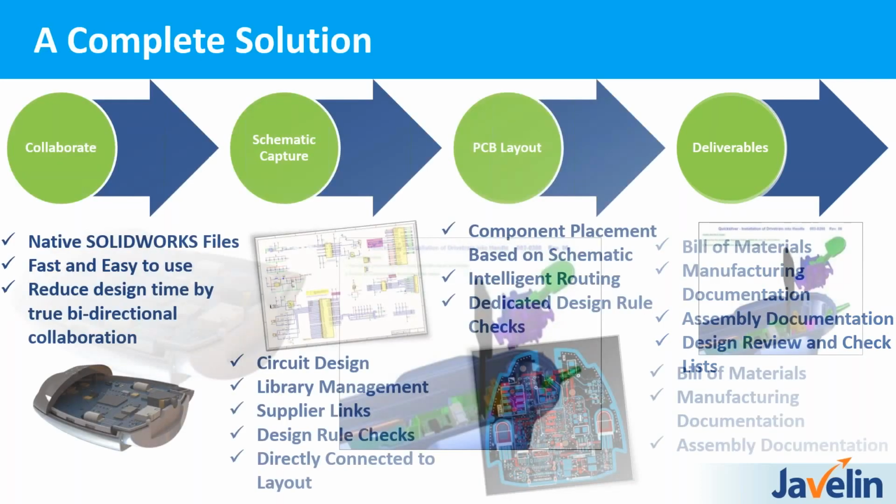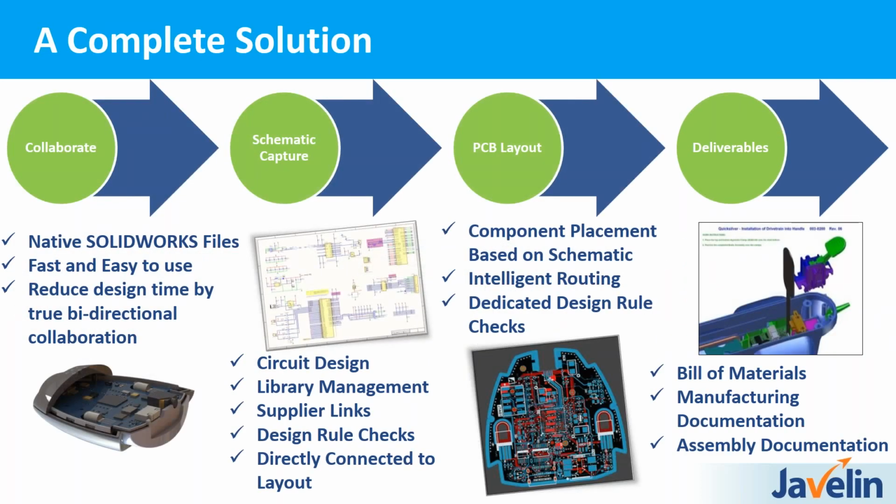So with that, it is a complete solution. We are able to work in a native SOLIDWORKS environment. The information is bidirectional between the two applications. We can work in a schematic capture environment where we have all the information from a schematic perspective. You can manage our libraries really well. Design rule checks exist both on schematic and PCB end.